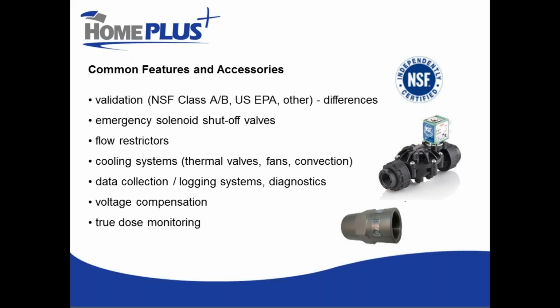Obviously, if there's a power failure, the UV light is not going to be operational and it's not disinfecting the water, so that solenoid will close. There's usually an internal or external flow restrictor that restricts the flow rate of the water to whatever the regulated or validated capacity of that system is.